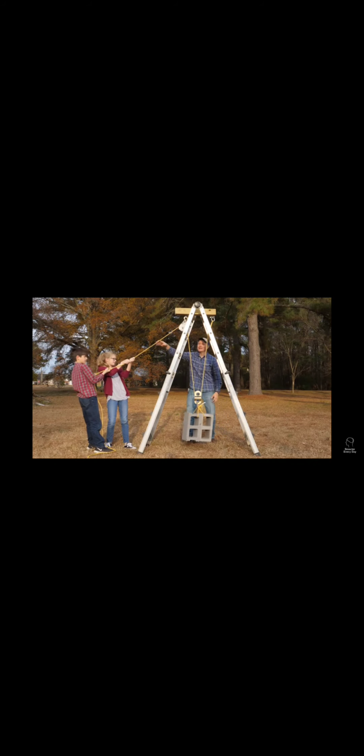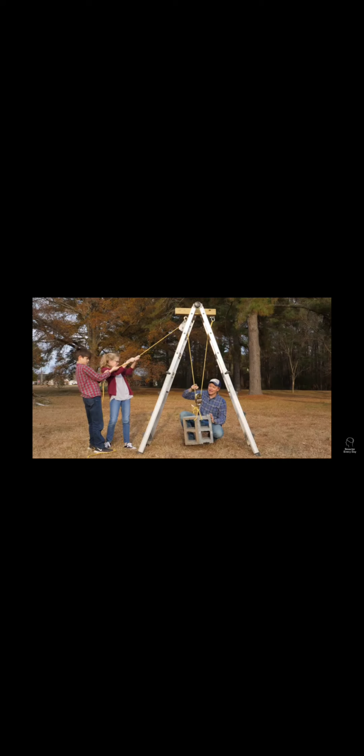The tension in the rope right here is being redirected by this pulley because that's what pulleys do. They redirect force. But down here with the snatch block, we're doing the same thing. We're redirecting the force. But you have tension in the rope and tension in the rope. So all you do is put tension in a rope somewhere, and then you add up as many ropes as possible on the thing, and that's how you get mechanical advantage. So in this case, how much force is on the cinder blocks? Do you know? 2 times the tension.